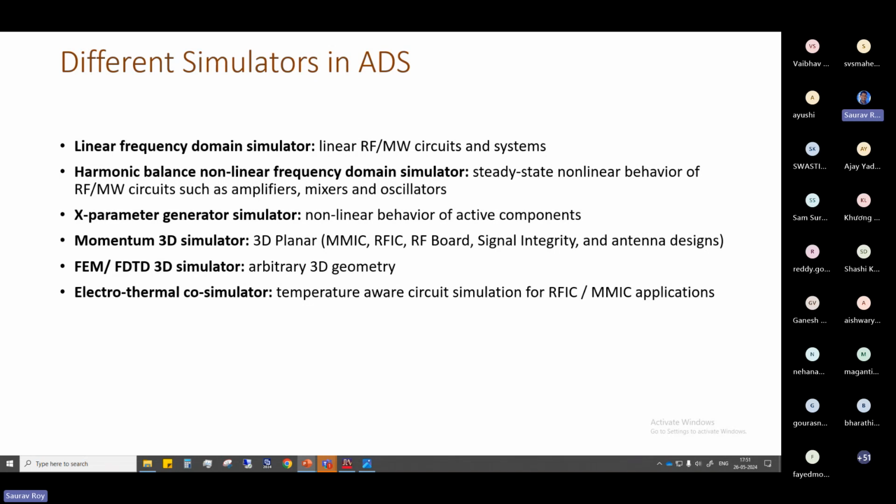Now the thing is, oftentimes in our simulation, we will have not only a single carrier component, but we will have the harmonic components also. Like let's say we have a 4 gigahertz carrier, but because of the hardware imperfections, or the imperfections in the LO local oscillator, it will generate multiple separate harmonics, right? So you will have power in the nearby frequency components also. To simulate that, the X parameter concept has been given. This is just to see the nonlinear behavior of components.